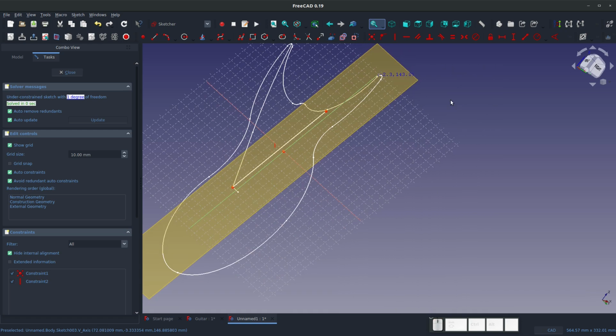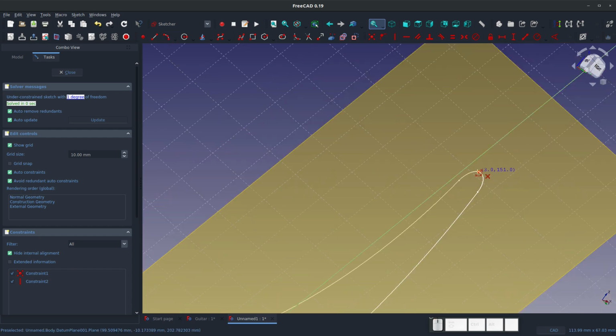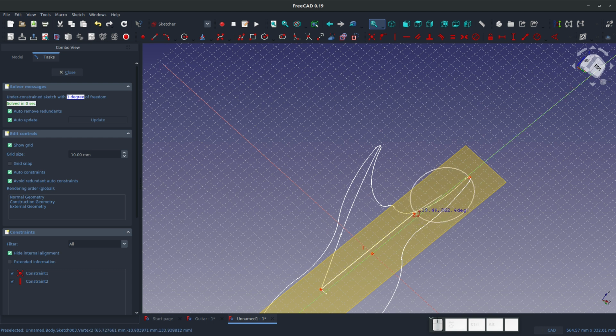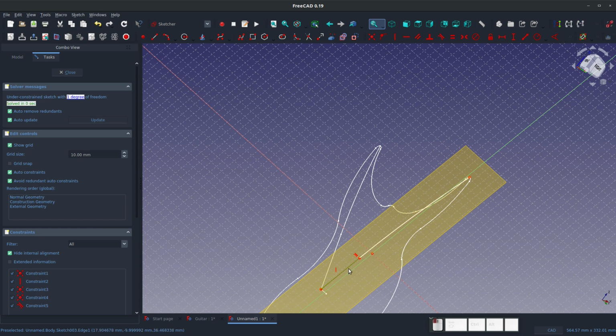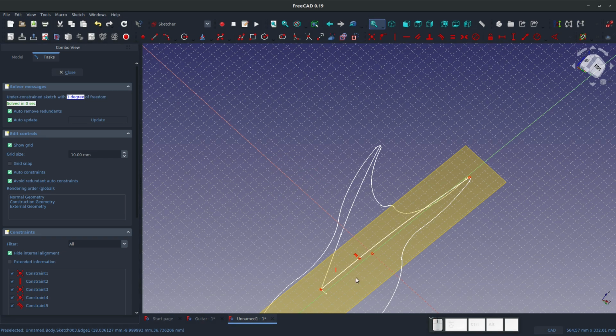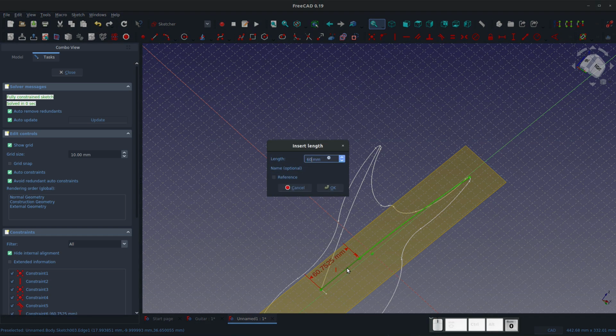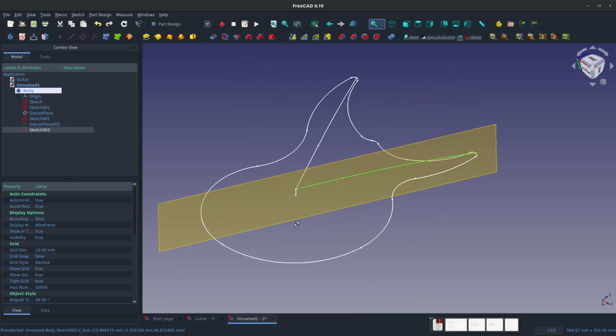Let's go straight for a little while, and then I can import that 3rd point there that we've created. Another arc. Make sure that we hit the T key and that our sketch is tangent. I'll hit Shift V for vertical dimension. There we go, 60. And we have another part.